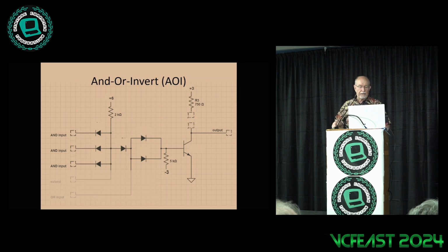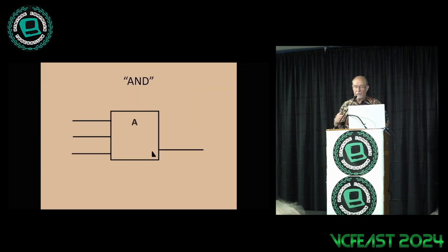There's some additional things in here where you can extend it to have more inputs. So if you want to go from a 3-input AND to an 8-input AND, you just add more diodes to the extend pin, for example. So very handy little device.